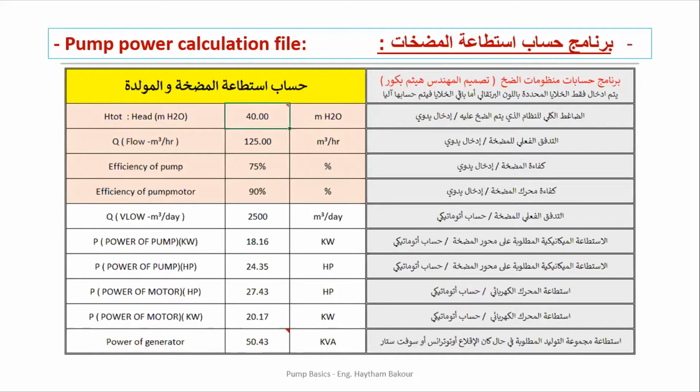And then we have some losses of 25% in the pump, so I have around 65% actual efficiency. So for every 100 kilowatts, I throw away 35 kilowatts. So when I use a pump motor with less quality and less price, maybe I'm reaching a higher loss, and this is not efficient at all.